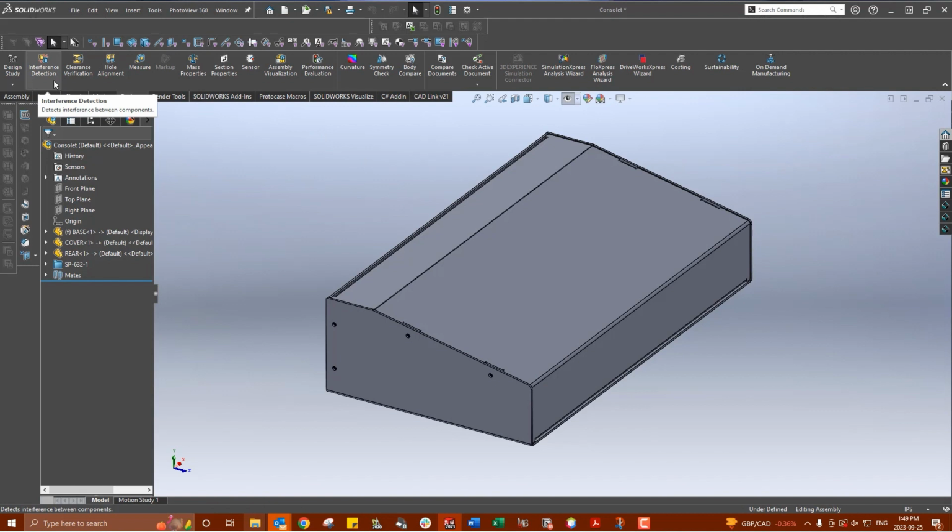Now, the trick using this tool, if you have fasteners in your model, is to only run it on the sheet metal parts. The reason being is that most, if not all, fasteners that are installed in your model will always have a coincident mate, or will be touching your parts in some form or another. This will provide you with a ton of interference warnings that you really aren't concerned with, and there's no need for those warnings to slow you down, right?